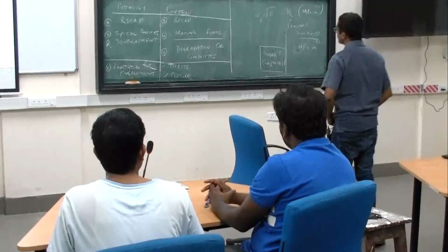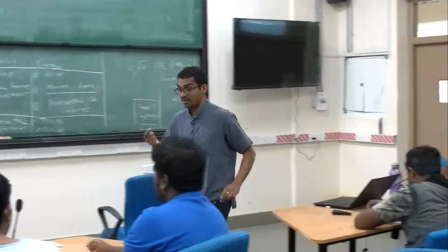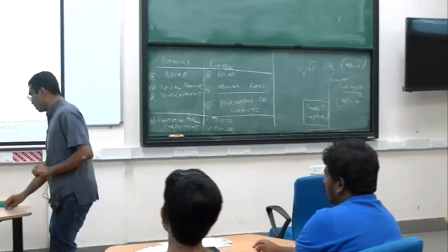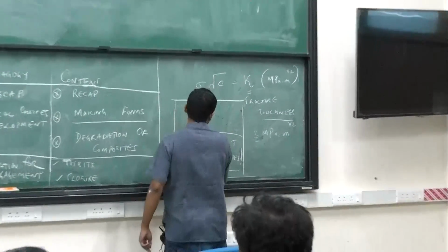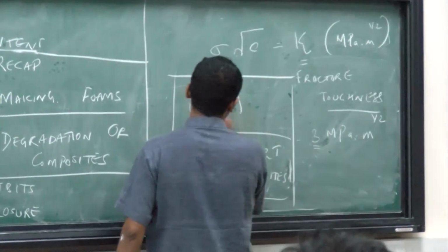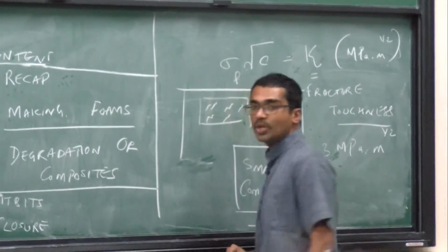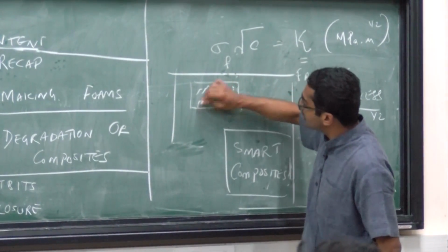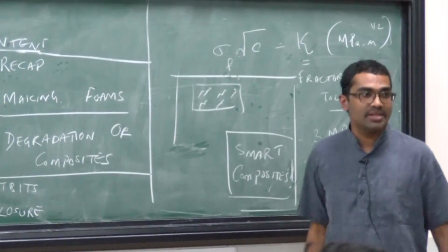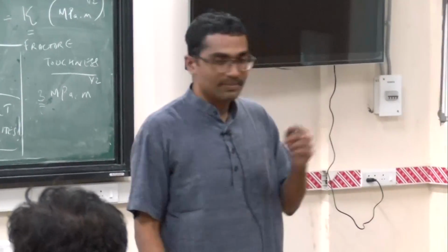And also those points can be places where a lot of electrochemical corrosion can happen because it's a very sharp point. So that's a very, very interesting suggestion. So you basically have a matrix, and in the matrix you have these dispersoids that are sharp, and so these could be regions where a lot of electrochemical corrosion and also stress concentration can actually occur, right? So that's an interesting point.